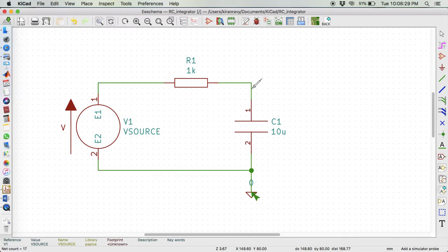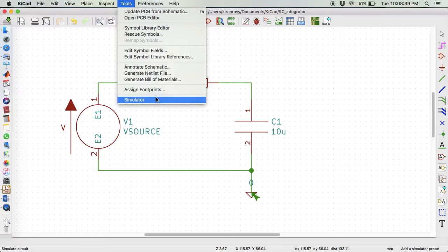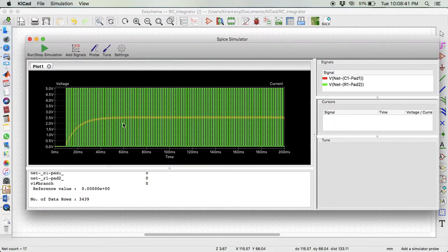So at this point I want to observe the waveform, so I click there, and this is the input waveform. I click there also. Then I go to the simulator again. Let's see what waveforms are there. So clearly the waveform starts after 10 milliseconds. Your input starts after 10 milliseconds. You are observing a window of 0 to 200 milliseconds because that was your settings in the transient.